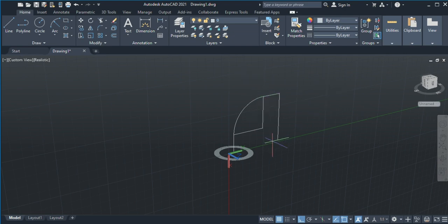Usually, if you operate with the UCS, you need to make sure the UCS goes back to the world UCS. So UCS, you can use Y and then put negative 90, or you can just say W for world. Now you just need to join the lines, and then you can sweep. Delete the reference line that we don't require.